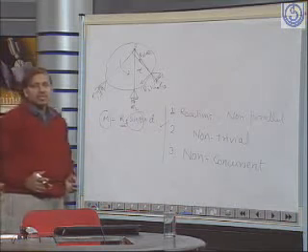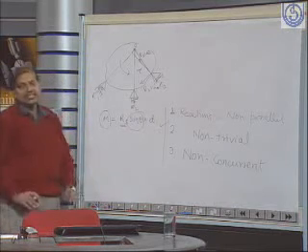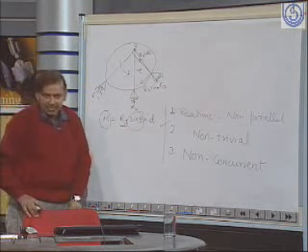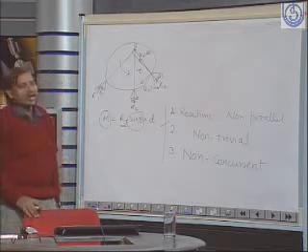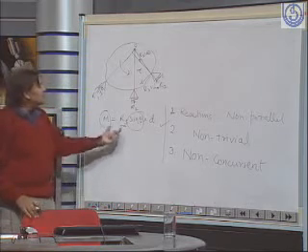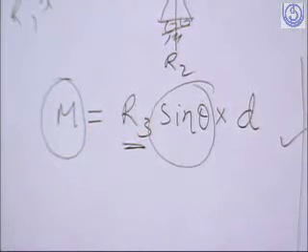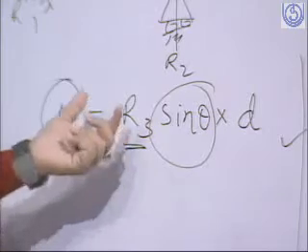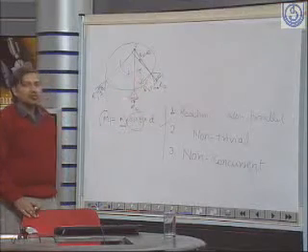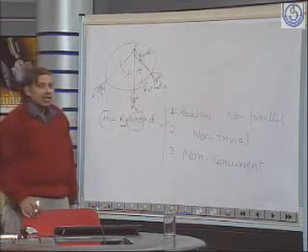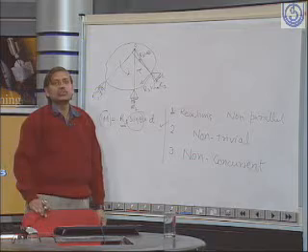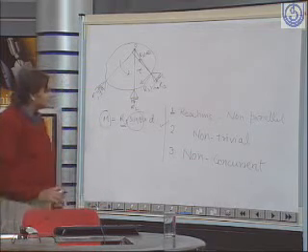So there will be a finite restraint. Maybe it is appreciably high, but it will be finite. So if you put a condition that it should be infinitely strong, then the external support may break and the structure is not good for stability.